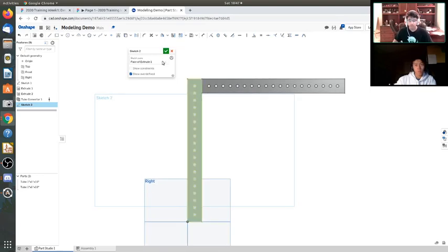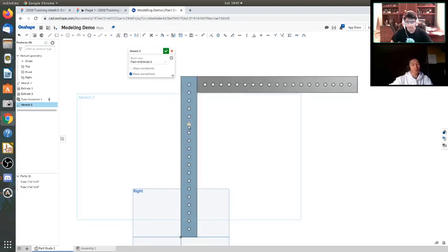So I mentioned how you don't want to be losing a lot of time in build season. One way you can do that is make sure all of your stuff is built around this adjustable box tubing model where it's all really robust. If you need to change a length or something, you can just cut the existing tube down to size instead of remaking and remachining the entire thing. And that can save a lot of time.